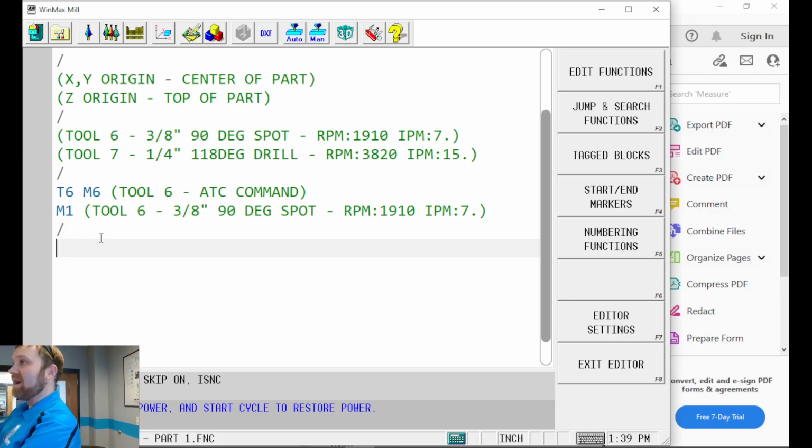Take the go, no-go gauge and measure and make sure everything looks good. Once the gauges aren't working, then hey, what do you think? Well, you probably changed the tool. You've been running it for a few thousand parts. It's probably getting worn out. Okay, yeah, we'll do that. They do know how to touch the tools off. That's a good thing. All right, but that first run through is on me. I'm the machinist. I'm the programmer. So I got to make sure that it's good.